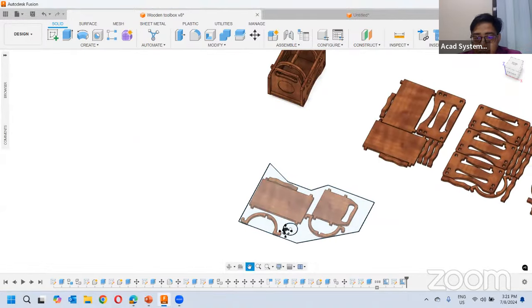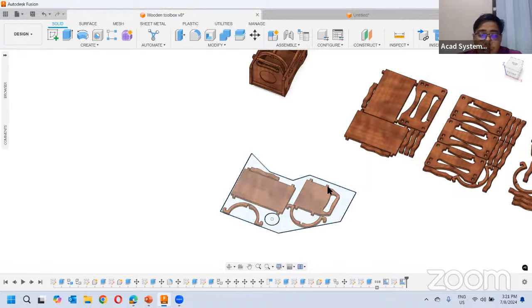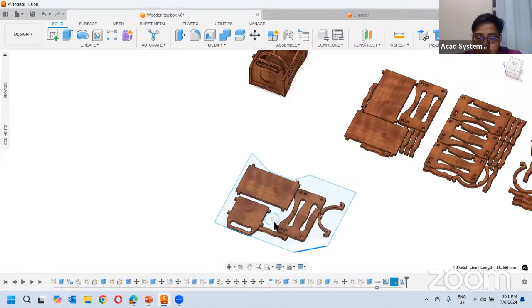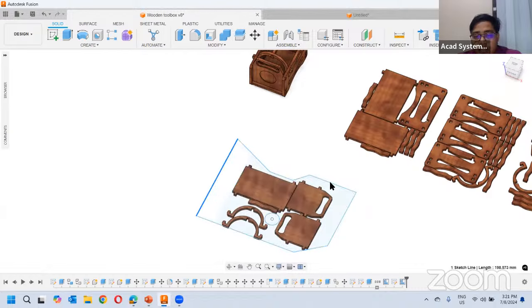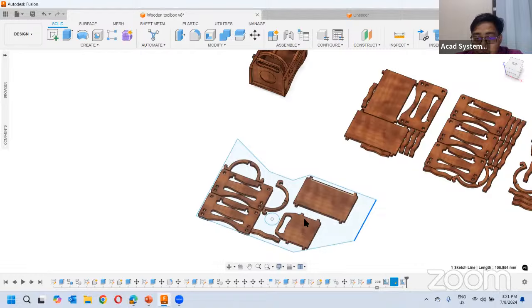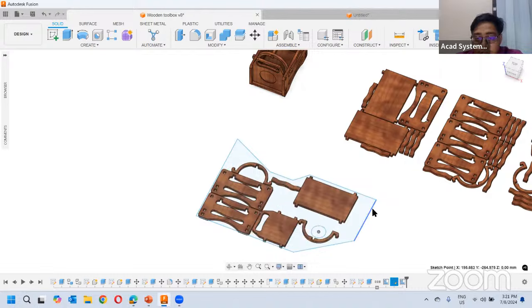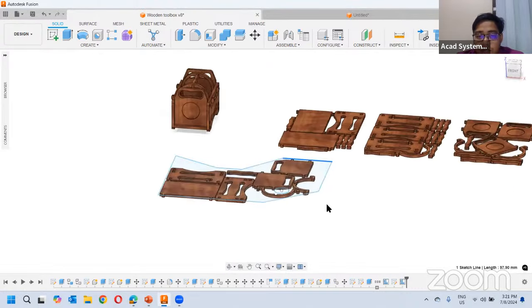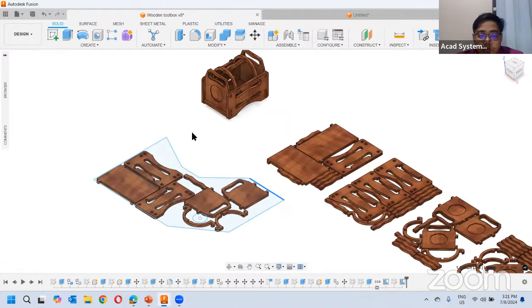And if I were to have a different type of raw materials or envelopes, I can also edit this sketch here. Right? So maybe I have slightly bigger space for the raw materials. If I do some editing, you can see that it will be updating and try to fit everything inside. As long as it's able to reach, it will try to put it. If I try to move this hole here as well, it will try to rearrange as well. Currently, obviously, I need to have much more space. Now that I have done that, I have this arrange feature able to work on the leftover of the raw material. So that is basically what I would like to share with this Visual 360 arrange.